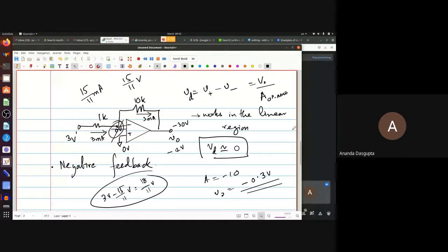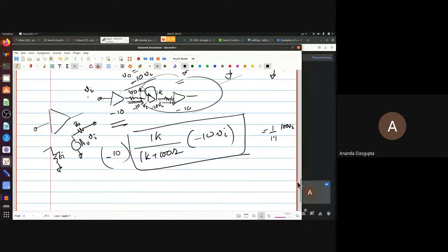So the unity gain buffer is what you have to connect in between in order to prevent the loading. That's what the buffer's job is. So despite the fact that it apparently does almost nothing, it actually does a very huge thing as far as practical applications are concerned. Anything further?